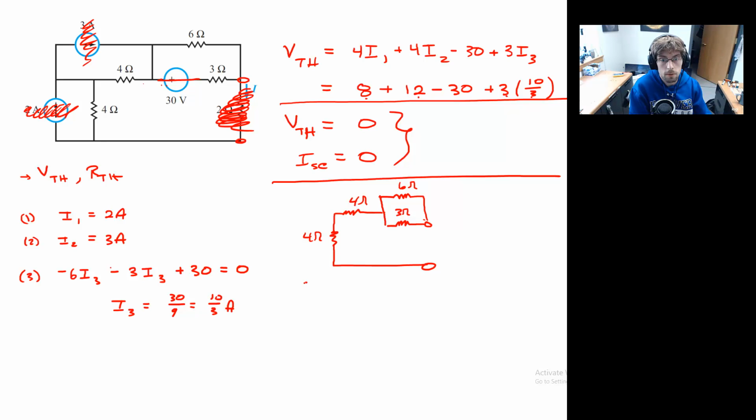Okay, well, that means that we have to calculate this 3 is parallel to 6. And then we're going to have to add in that 8 ohm resistor. Okay, so call this one equivalent or Thevenin. For this situation, those are interchangeable. We have 1/3 plus 1/6, to the -1, and then I'll put a +8 in there.